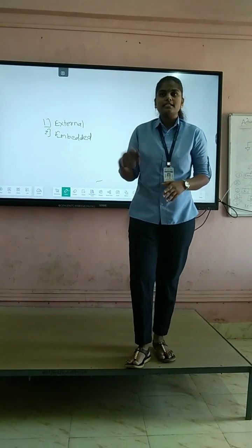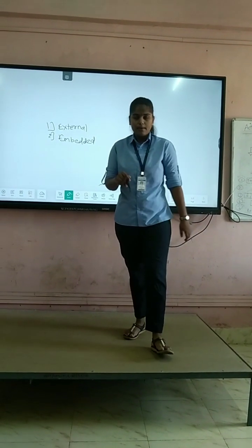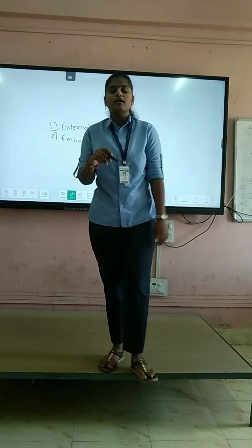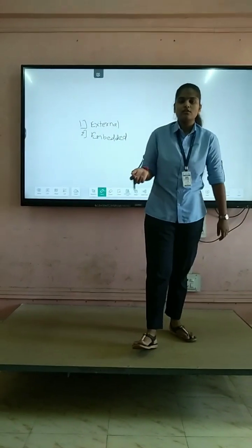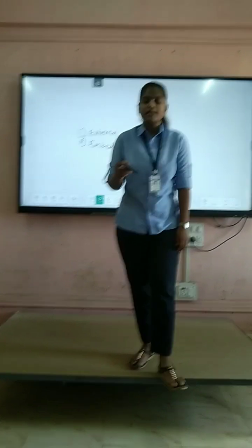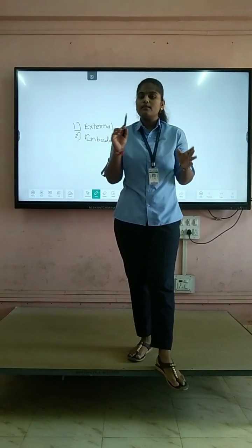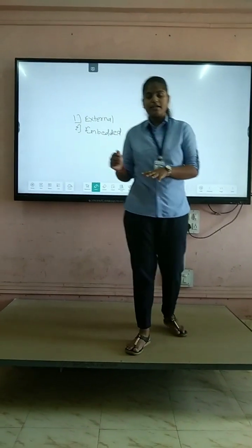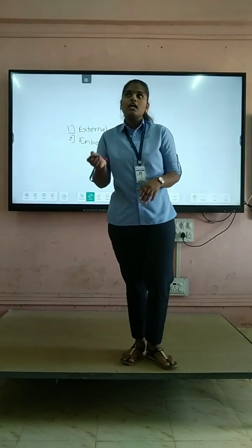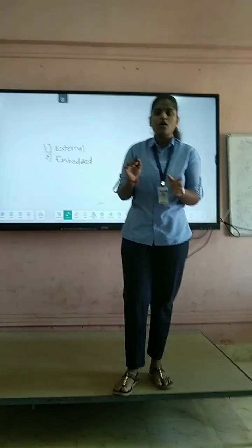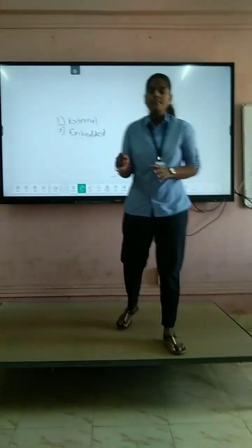And in the Harvard architecture microcontroller, program and data memory have separate address units, and buses are also separate. Whereas in the Von Neumann architecture, there is a common memory unit for storage of data and program.